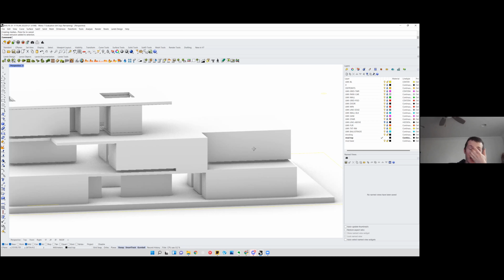They would just be alongside the column, and we would punch a hole in the deck for both the drain and the column to go through, or the drain to go through alongside the column.